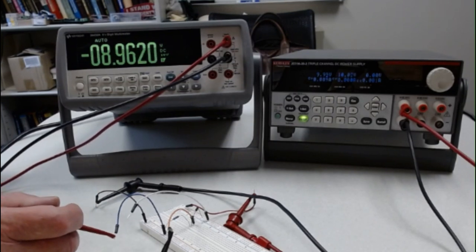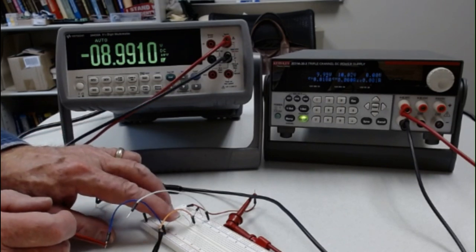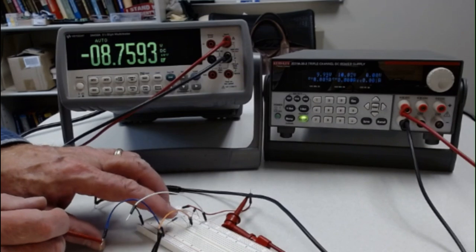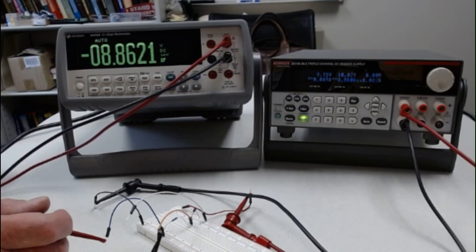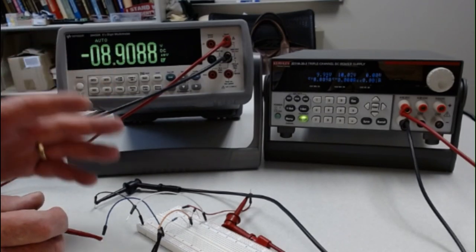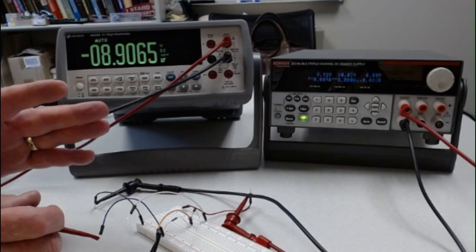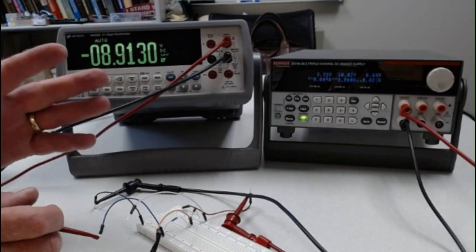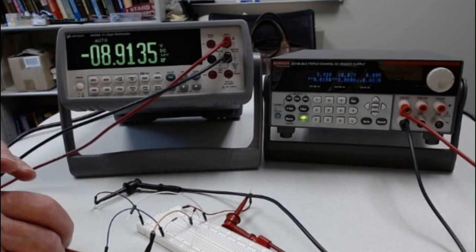So we could go back and measure current, but we realize that we've got a 1K resistor here. If you measure the voltage across it, you're going to get the current in milliamps. It's a very accurate 1K resistor, so all you have to do is take the voltage across the resistor, divide by 1,000, and your answer is in milliamps. We could prove that by just breaking this circuit apart, but we don't have to. We know that V equals IR, so I is V over R, and we can get our I that way. So you basically have now all that you need for the voltage across the diode, voltage across the resistor, and the current through the circuit in the forward direction.